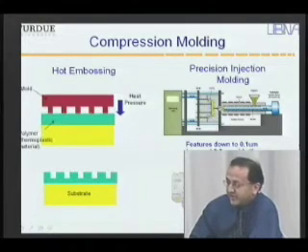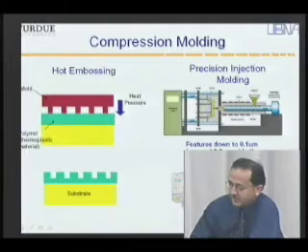This is the process of choice for making plastic cartridges, for example, or any sort of plastic material that you find around you that needs to be made in large quantities. That's made by injection molding. And these injection molding processes have now been perfected to a point where you can go down to features of 0.1 microns and 0.6 micron wide, for example, for a CD. Those are injection molded tracks.